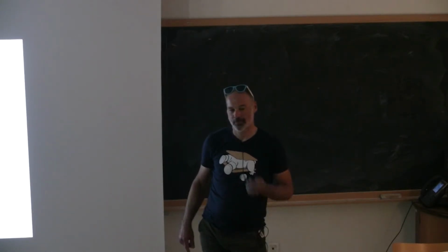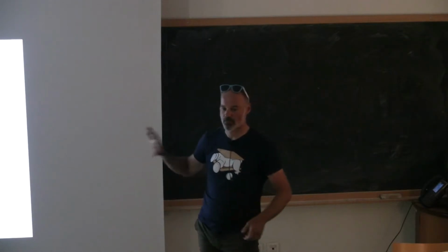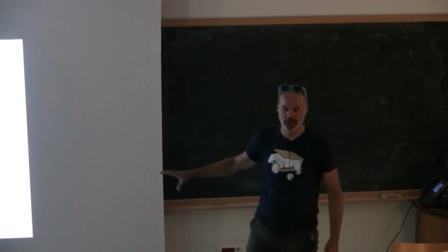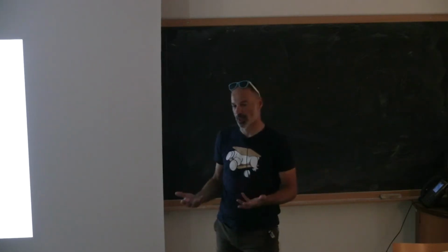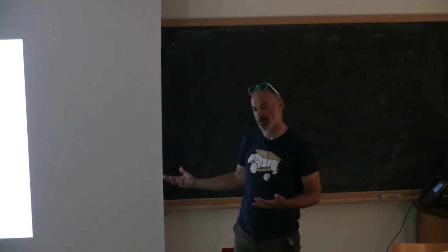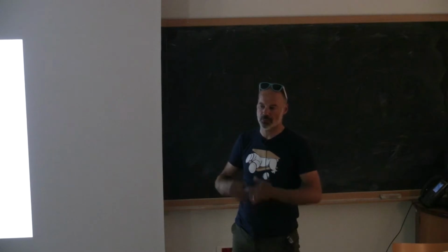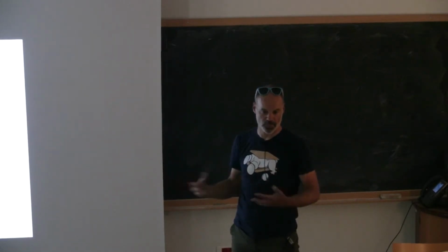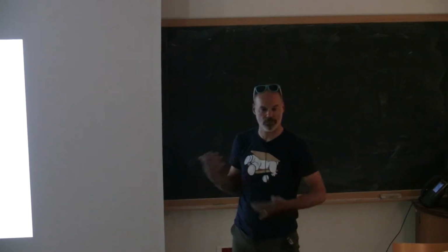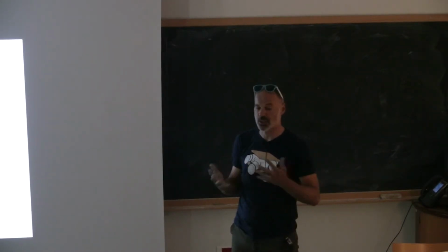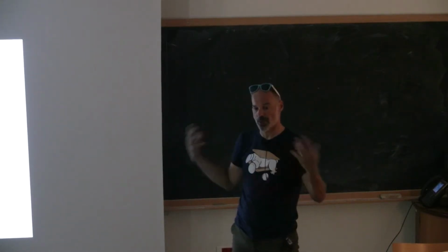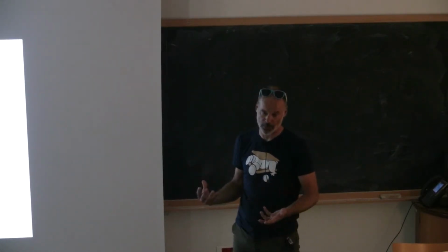Okay. Point one, yes. All of the things you said are in my sorptivity lecture, in the early time lecture, and I skipped over that just for time. But you're right. But typically what limits runoff production in these dry systems is still K. And we've played around with Van Genuchten functions and Van Genuchten parameters and things like this. And it just, for short-term, very dry systems, plays less of a role.